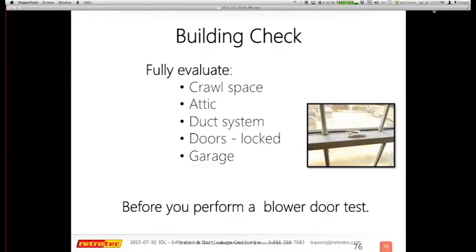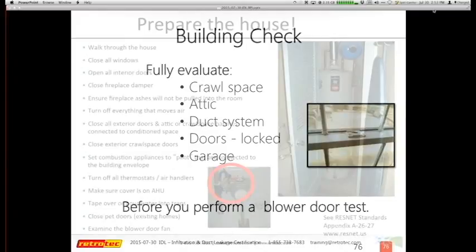Sometimes we actually do existing homes and we show up and we didn't really go thoroughly into the crawl space or attic, evaluate the duct system, or check that the doors and the windows are locked. All those kinds of things make a huge difference. So even if it is a brand new home, you want to make sure that there wasn't a water leak in the crawl space, or the attic doesn't have some kind of issue or missing shingles that would have actually affected what you might actually be doing to the house itself.